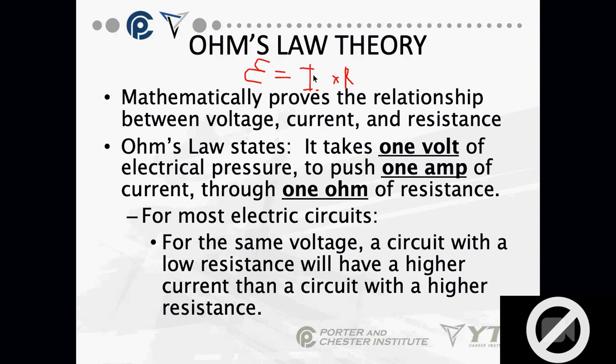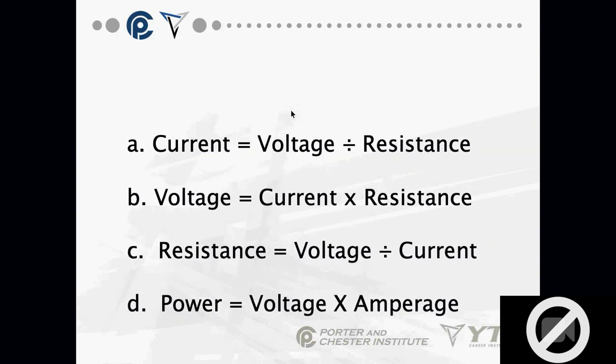So just, again, always remember Ohm's law, okay? E equals I times R. Once you have those letters, you can do anything with them. So current, you take that same formula, you redo it, okay? If you're looking for current, which is I, you take your voltage divided by resistance.